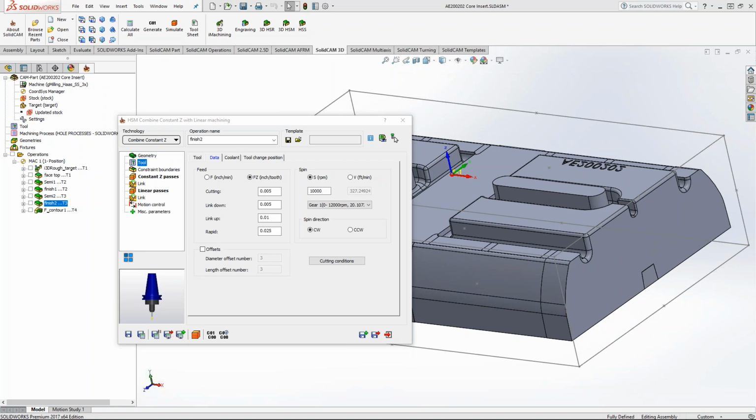Now, with the harder material, what you'll need to take into account is the material you're taking off. The harder the material, the less stock I leave. So let's say I'm cutting P20 at 28 Rockwell and I was going to finish with a 1/4 inch ball, I may leave 7 thousandths for a finish pass.